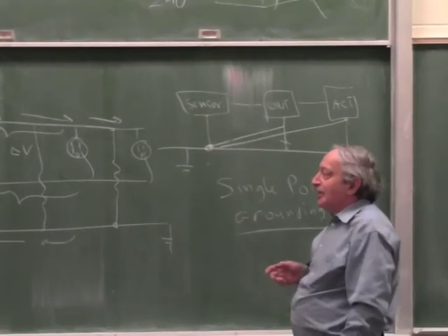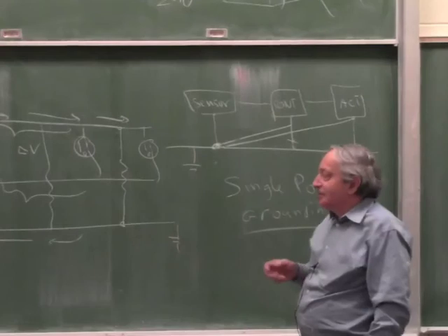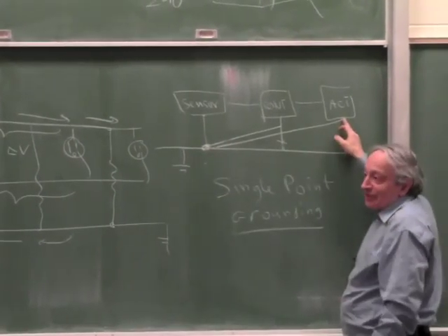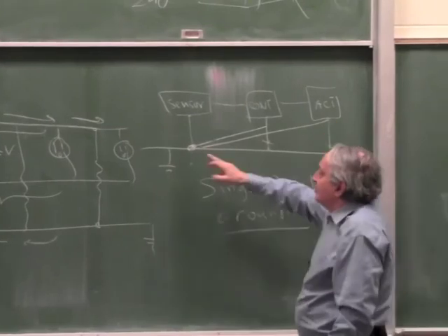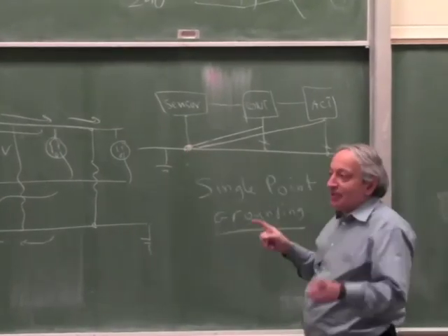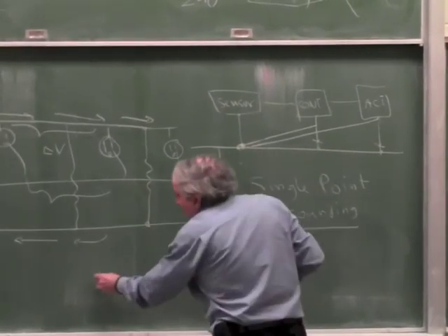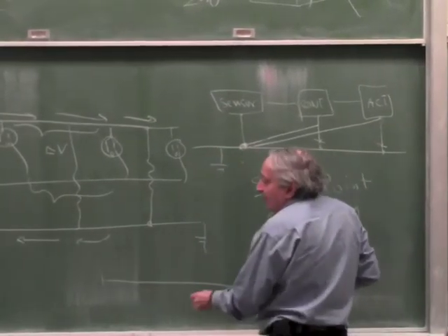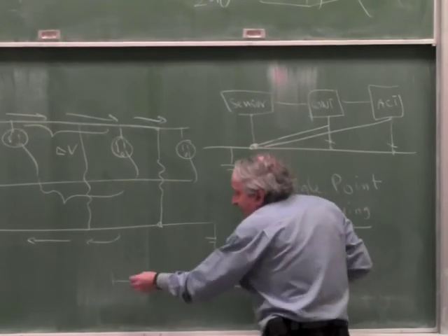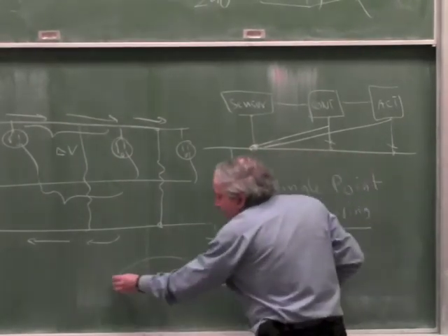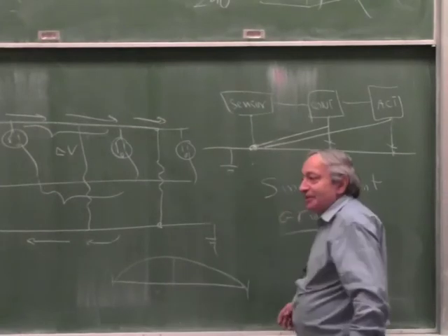And the problem you run into at high frequencies, this can be a fraction of a wavelength, or more than a wavelength, and then you can have 0 here and maximum here on the same wire. Because I mentioned before standing waves. When you have a piece of wire, and this piece of wire is half a wavelength in length, you can have an electromagnetic field which is 0 here, and maximum in the middle.